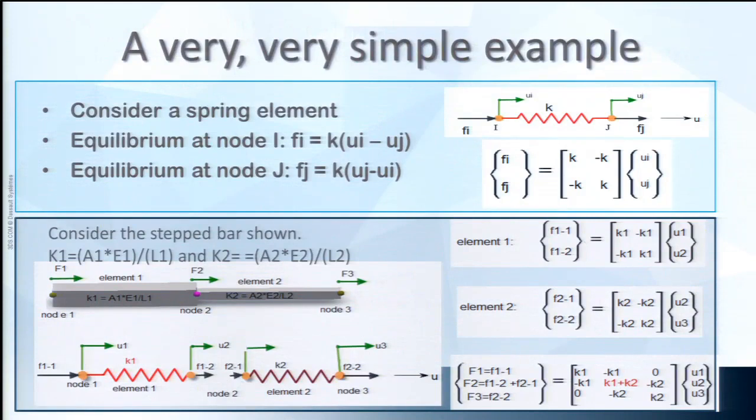So why do we use simulation, and why are we doing this to solve these problems? Well, here's a really basic one. See, I broke it up into two elements or two springs, and this is the mathematics behind it. It's F equals KD. K is the material property or the strength. F is our force or our boundary conditions, and we measure the displacement. And we build this matrix, and it's a problem that we can solve. Now this is a very, very simple 1D problem, and there's 3 nodes in there. Imagine problems, like most problems, are about 100,000. Who would want to solve 100,000 by 100,000 matrix? Anybody? That sounds like a fun Saturday.